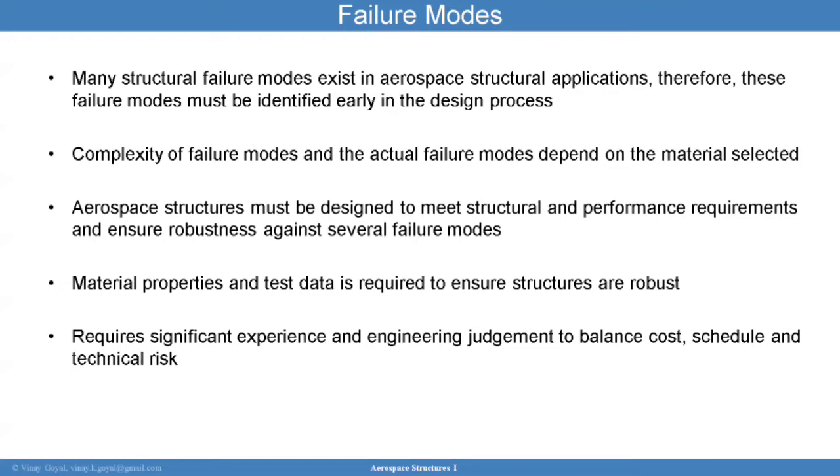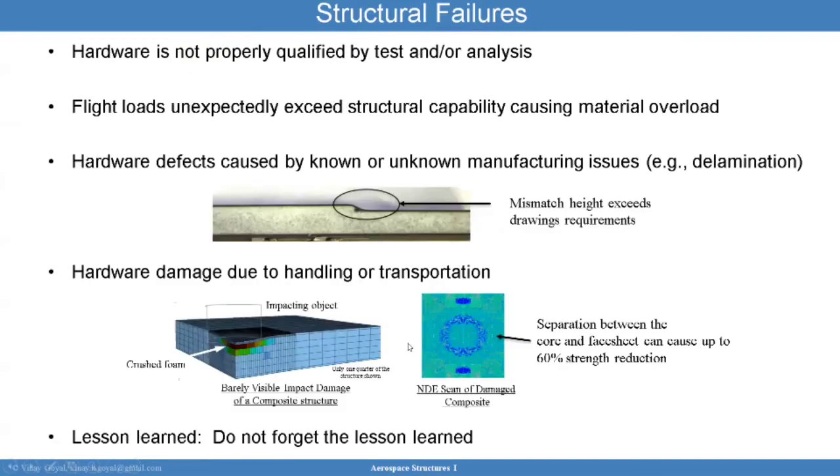And so what I want to point out also is that structural failures do occur for a variety of reasons. One of the reasons is that the hardware may not be properly qualified by test or analysis. You thought that the hardware was qualified to the low levels it will experience in service, but then you did not really account for the test like you fly differences. When you fly and when you test, you're going to see different conditions. You cannot test everything on the ground.